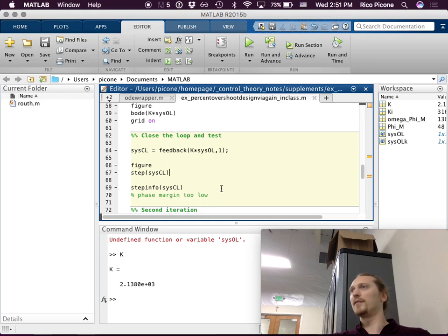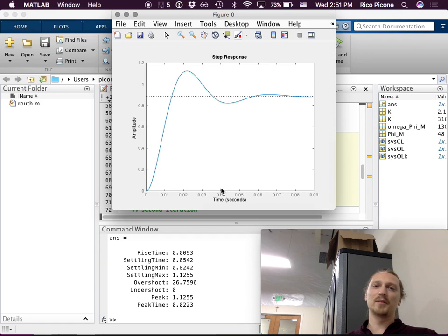We know that. We already determined that, which is a good thing to do at the very beginning, is say, what range of gain is going to be stable? Because your Bode plot design can lead you very wrong unless you're always checking back the Nyquist plot. Make sure that you're not going to go unstable, because the Bode plot will not give you a warning of that occurrence necessarily. It's more subtle. So let's take a look at the step response of this.